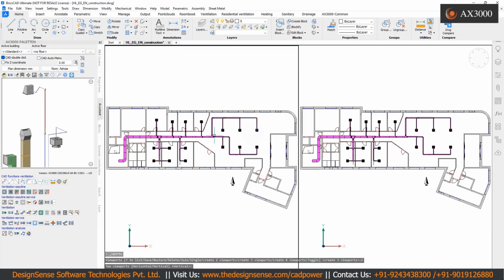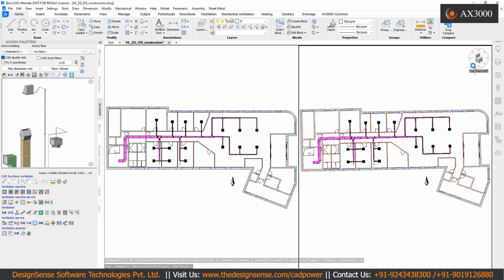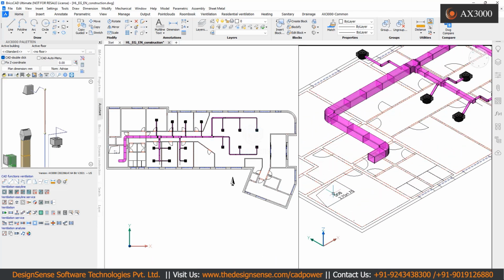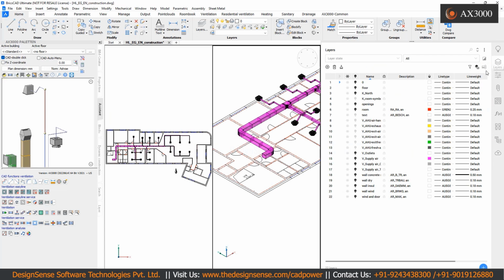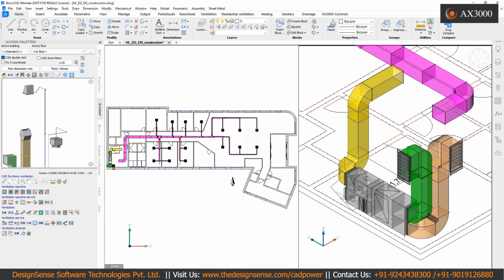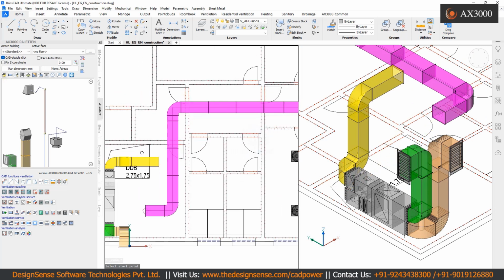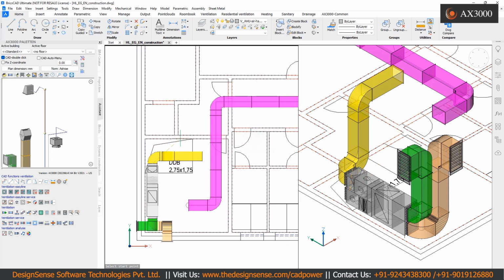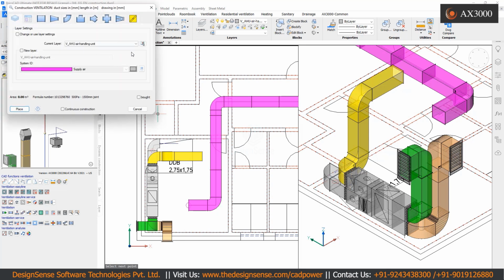Work with two viewports. And continue with another version of the drawing. It's called construction. I have switched on a few layers because this air handling unit and a few ducts are prepared, and I will continue the construction by starting on this flexible nipple, going straight to the wall. So it is enough to select the wall directly in the plan view or in any other view.